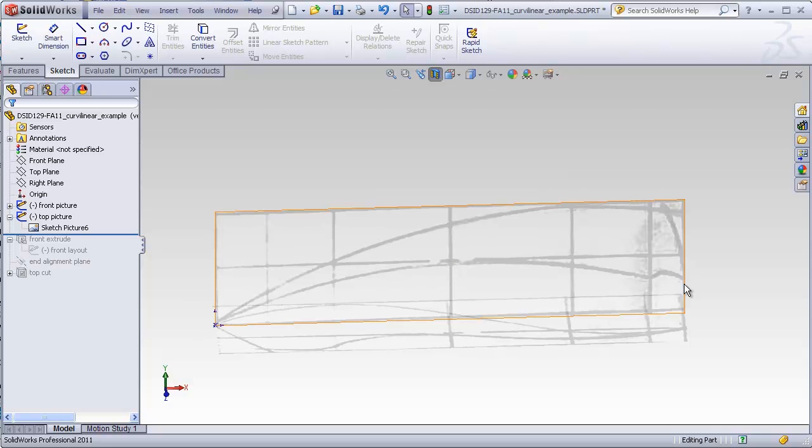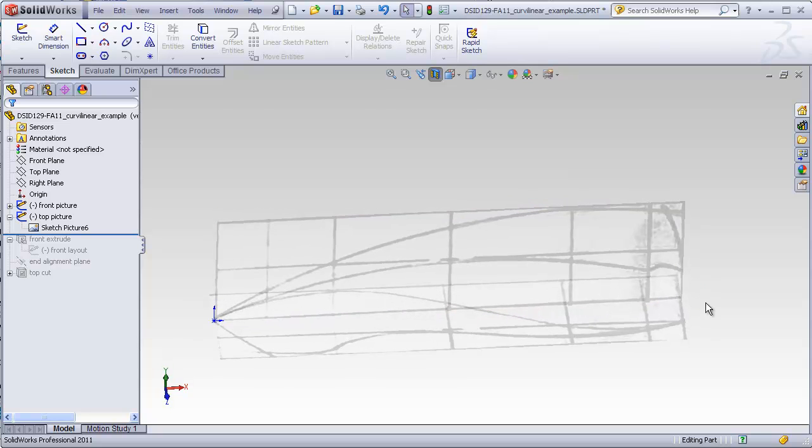This means not only making the images the same length, but also making sure that when we make our actual sketches, we have some sort of relation set up to guarantee that the endpoint of one sketch is in alignment with the endpoint of the other sketch in the x-axis.